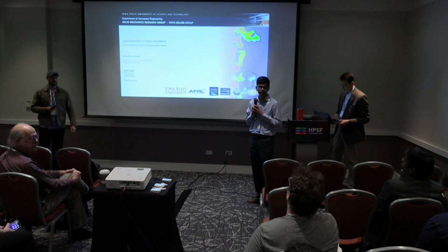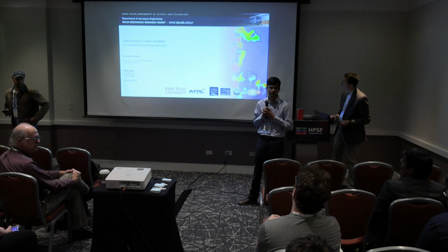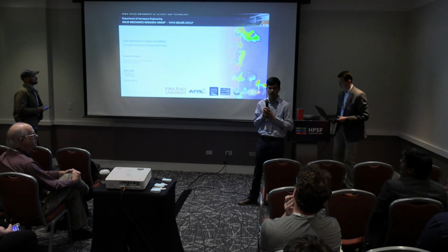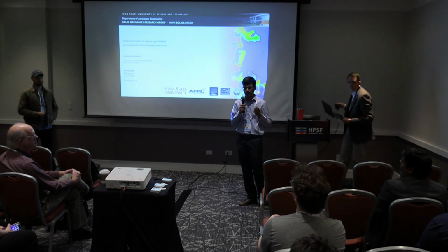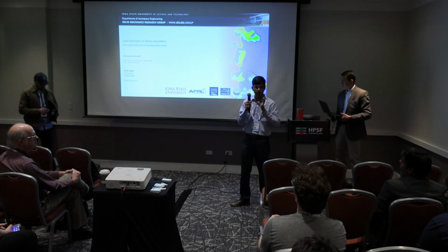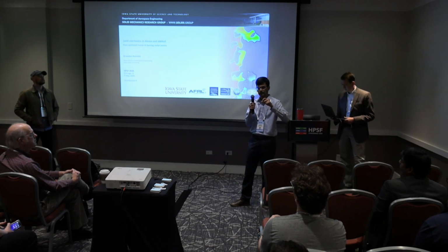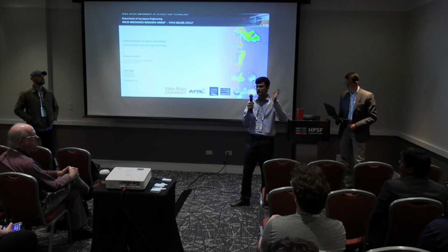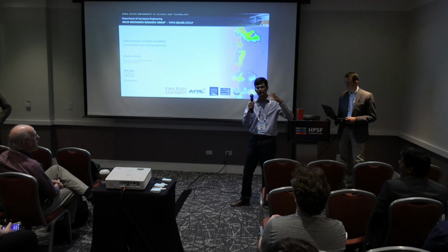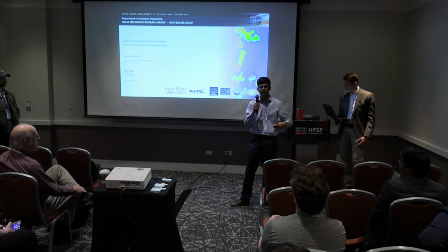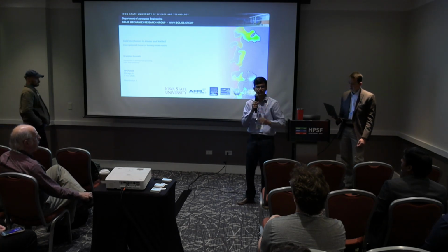Is there one more? I don't really know much about EB, so I didn't understand why you need to iterate the geometry to reduce the number of small cells if you're gluing them together in a later step. The way the geometry generation works in AMReX is that as soon as you touch one cell, because we allow only single cuts, the other cells are also affected. As you touch more cells, the neighbors start getting affected, and they may fall below a small threshold. This happens when you have lots of curvature.